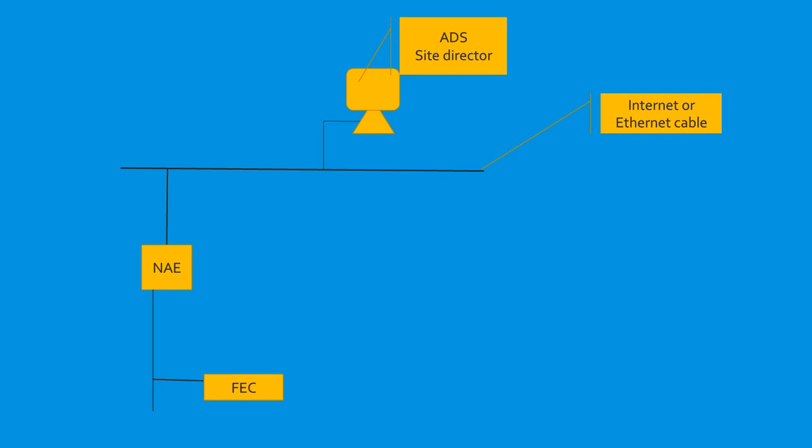FEC controllers are Field Equipment Controllers. I know, not yet another three-letter acronym. Yes, our industry, the building automation industry, is rife with three-letter acronyms. Field equipment controllers are located in the field. We mean by that FECs are located physically next to the HVAC equipment that they will directly control. One FEC may control a boiler, another FEC may control a chiller, and yet another may control an air handler or a rooftop package unit. Each FEC has its own software program which contains all the necessary features, settings, and instructions required to operate the equipment that it is attached to and controlling.